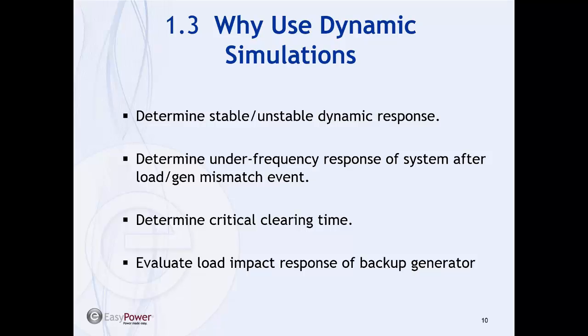Load flow is not going to look at it, and it's not a software limitation, it's an approach limitation, a calculation method limitation. Newton-Raphson or Gauss-Seidel, neither of those methods were ever designed to capture transients of a system, never. So any module in any software package that you find for load flow is designed based on those approaches, and they're working perfectly, including EasyPower. They're not designed for that purpose. If you look at over voltage, under voltage, transient events, you have to come and use dynamic stability.